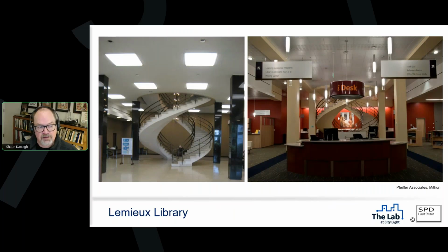They're providing some light within the space, but they're also providing something visual for you to latch onto and think, oh yeah, your brain interprets this as the space being relatively bright. Of course, the measured light level is a fraction, but it's a much more comfortable, much more interesting space to be in. To be sure, the surface changes, the column covers, the back wall, those things are all critical. That's part of my point. You can't have high quality lighting without high quality surfaces. You have to look at both of them together. It's part of one gestalt, right?